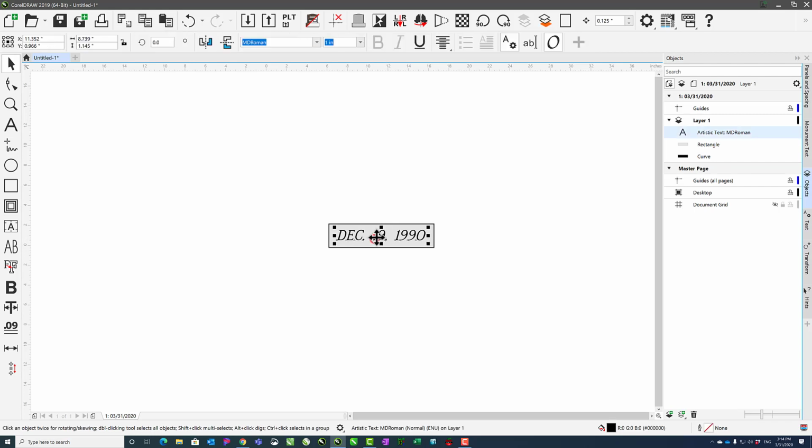If I wanted to make a duplicate, let's say I wanted to duplicate this text, I can drag the text to the right, hold Control so that it stays in line, and then while I'm doing that, hit the right mouse button, and as soon as I hit the right mouse button and let go of it, it'll give me that plus sign for the cursor, and then I let go of my left mouse and let go of Control last. That way it'll make a duplicate for me.